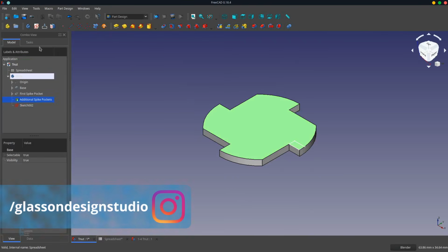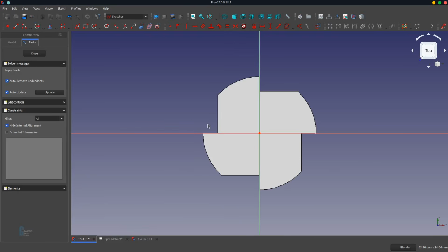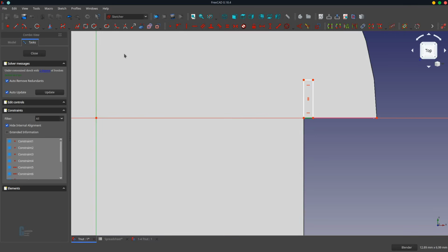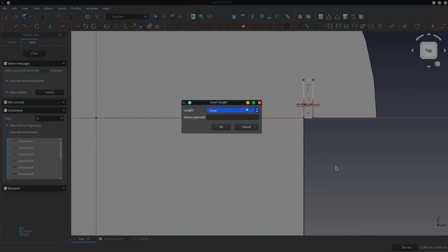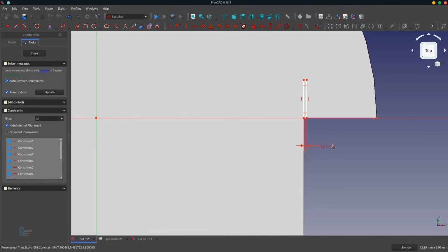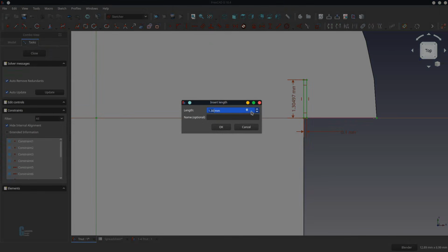I then decided I'm going to create another spike, and I'll use another sketch, and I'll use loft to loft it. So I went, all right, let's import that guy again. A little box here. There to there. We just made it 0.1 millimeters so that I could get almost a point at the top. And we made the thickness of it the material thickness.